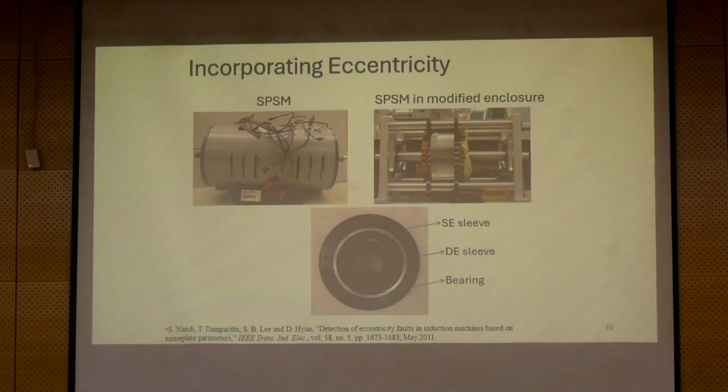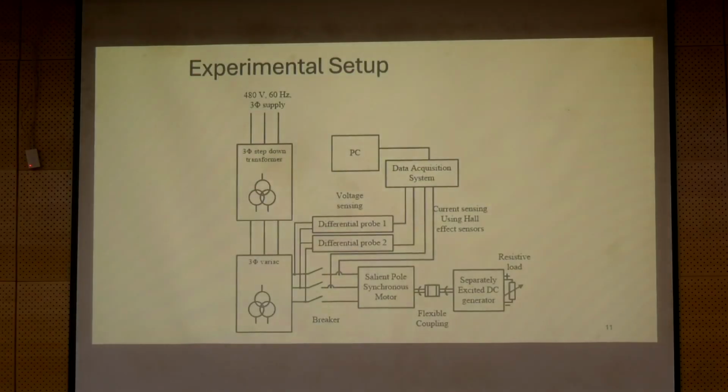Okay, so whenever you, and these machines are rotating at high speeds, right? So you have to be really careful. And because they are open windings carrying high currents, you need to be really careful as well. Okay. Accidental short circuit should be avoided. So in a setup like this, protection is critical. The diagram does not show any protection, but it is not how it will be.